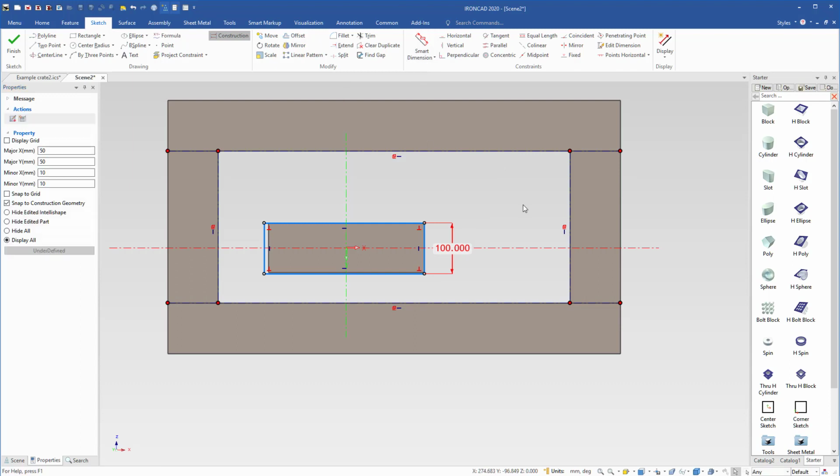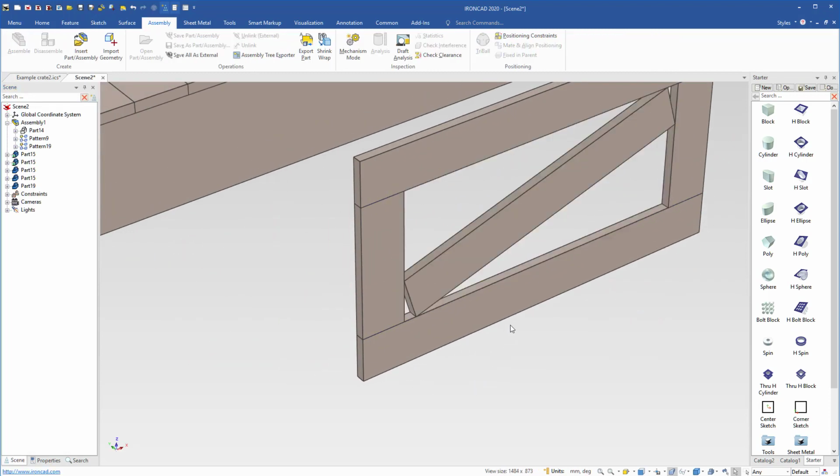So now all I need to do is use a coincident constraint to basically align this up. So I know I need this top point to be coincident with that. I need this point to be coincident with that. So it gives an angle relationship. I can do the same thing for this bottom and this one to this side. And notice it has to maintain 100, so it just moves the object to fit oriented inside of there. Of course, you can do mathematical formulas to drive certain heights if you want inside of here, but in our case, I'm just wanting to move and adjust and be coincident to both of those edges and maintain our height as it adjusts and sizes parametrically. So now I've built that shape, I've got it all ready, I can just hit finish. We now have our board.